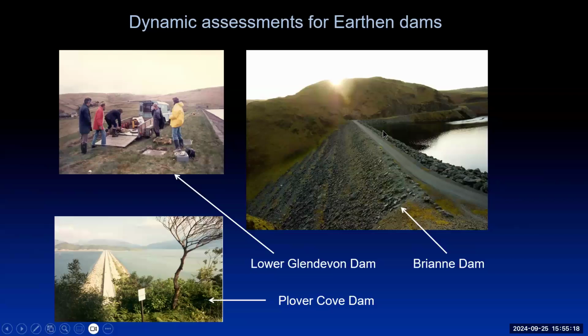Earthen dams behave monolithically. Like it or not, they do actually. Their modes of vibration, they sway, they vibrate in the same way that concrete dams do. But being earthen, they actually consider that the surrounding countryside is always part of them. So there is not encastre applying at the edge of a dam, but the surrounding countryside also shakes around. So we put vibrators on these entities, these dams, and shook them, and actually had quite a big argument about making measurements that we could only stop at the end of the dam, whereas in practice, no, we needed to measure the surrounding countryside as well. Isn't nature wonderful?